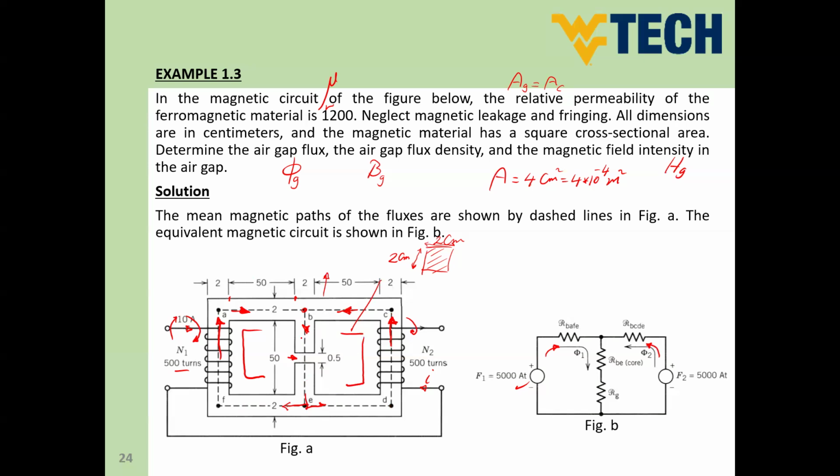So we can now make many paths for our reluctances. We can consider that we have a reluctance for this part starting from letter B, from point B. So we have B, A, F, E. This is the left C shape. So we have a first reluctance, reluctance BAFE, and it will be identical to another reluctance of the C shape on the right-hand side, which is BCDE. We call it by these letters, guys, which is the same length, or average length, of our magnetic flux path.